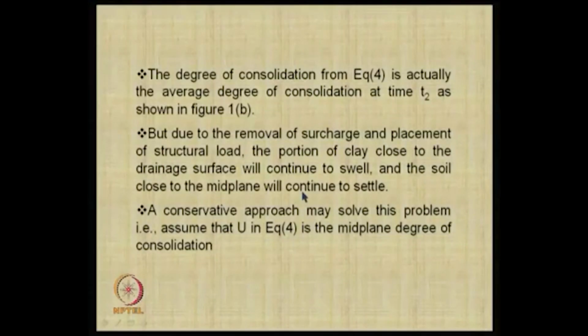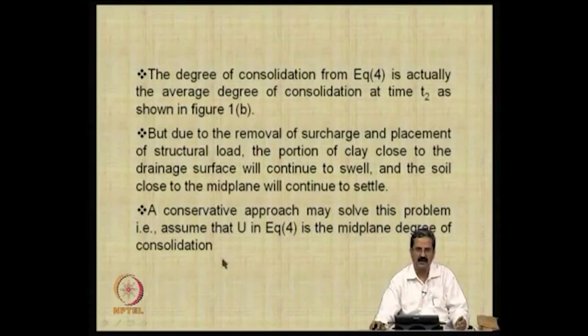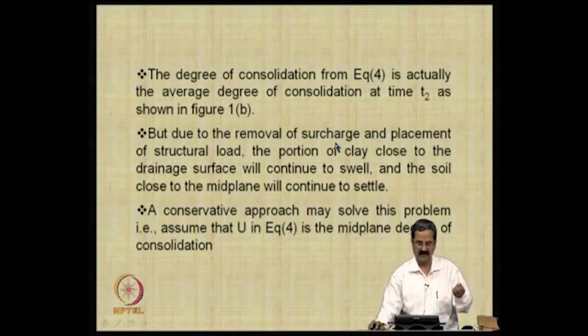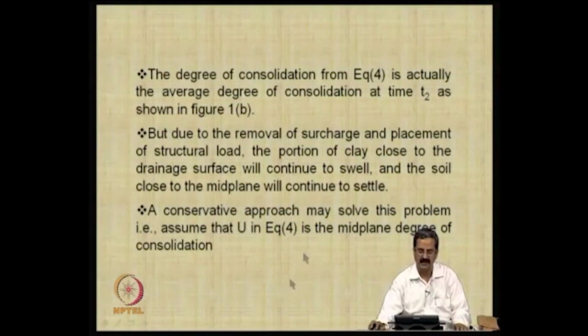So, we assume that, with the removal of surcharge and the placement of structural load, the portion of the clay close to the drainage surface will continue to swell because you removed the load. So, there are some minor changes in the soil, and soil close to the midplane will continue to settle. To balance out, there is an approximate assumption that the degree of consolidation is the midplane degree of consolidation. We are just trying to average it out like this.